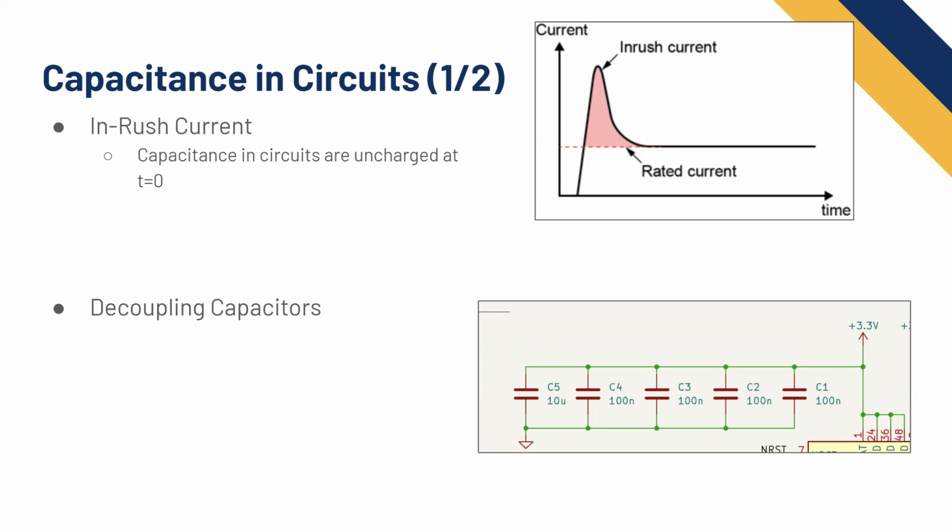And so you're swinging one of the nodes a lot, and these capacitors will source a little bit of current, absorb a little bit of current, source a little bit when the microcontroller is switching. But in this case, we don't have the resistors, so how do we compare? The resistor would be from your voltage source resistance to your power pin, but typically that's resistance or inductance. So it's easier to explain in the case of inductance, where let's say there's some inductance between your voltage source and your chip, which there will be inherently.